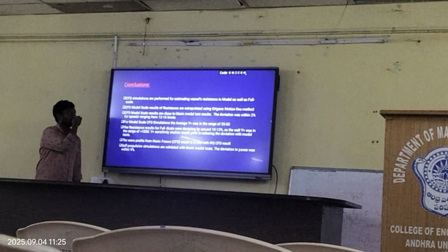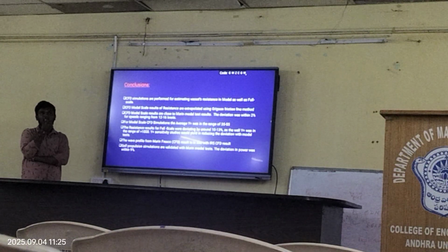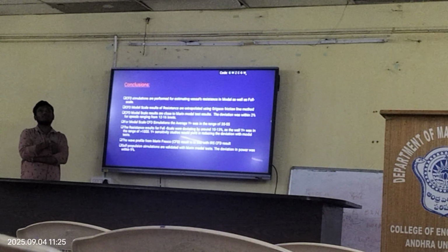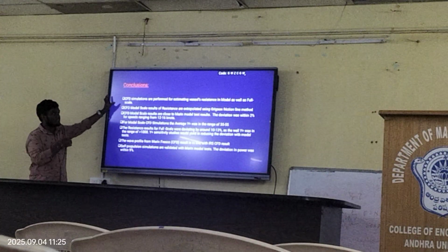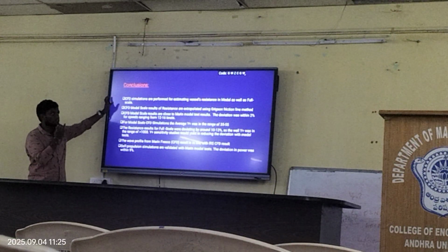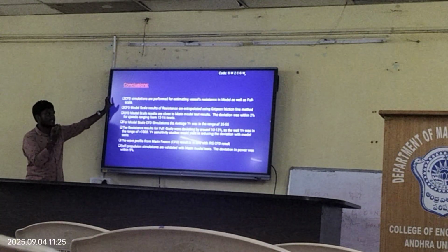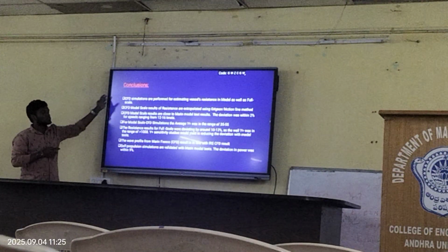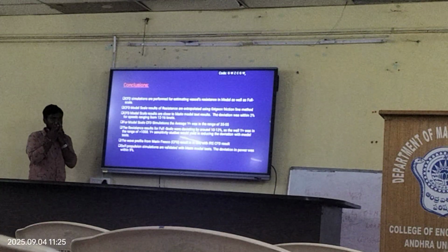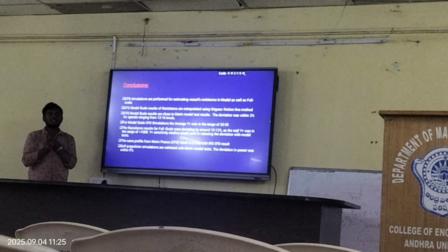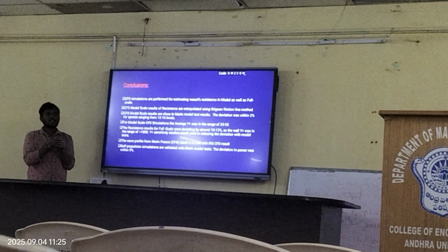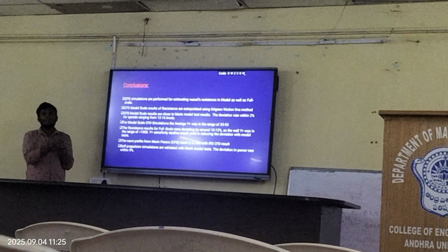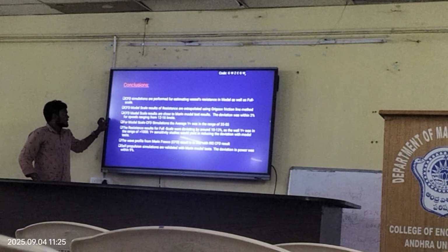So the conclusion, sir: I have learned everything about resistance and propulsion. I have revised my basics to deep concepts, and then CFD simulations were performed for estimating the vessel's resistance in model as well as full scale. And the CFD model scale results of resistance are extrapolated using the friction line. When extrapolating the results, I have seen that the model scale extrapolation results are very good and very accurate. But the full scale results are not matching with the standard results. Why? Because there is actually a wall y plus which is involved.